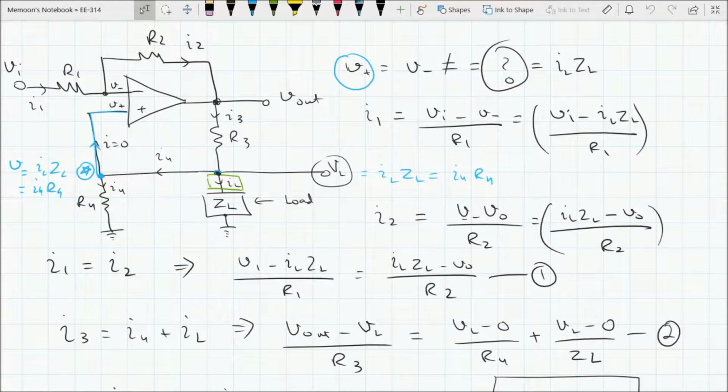So one application of the voltage to current converter is also discussed, and in other cases there are appliances, especially inductive appliances, that need a constant or a known current supply to operate, not a known potential. So we have to provide a known current to those devices to correctly operate them.